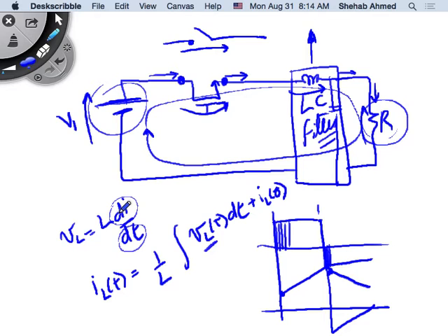So your di is big, and you did that very quickly. Suddenly you just opened, so dt is very, very small. So di/dt is a very, very large number. So V is a very, very large number. Now the voltage across the switch is huge because of what you did, right? And that's what happened in the video.